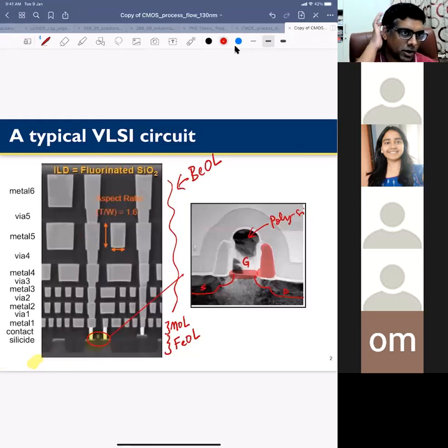We have already studied this in this course, right? If you have a semiconductor and it is contaminated with copper, then the copper will create a mid gap state. That means the semiconductor will not be pure. It will have defect states sitting right at the mid gap, and it will have issues in the recombination and generation process.